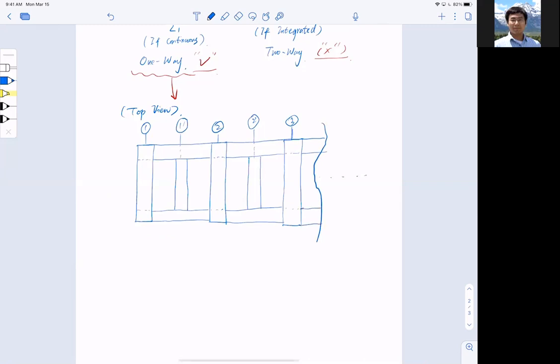Sorry, I'm trying to draw as clearly as possible. This is still an ugly drawing, but anyway. You see immediately that I have some overlapped column support underneath. I need a column underneath this transverse beam, so the shaded areas are the columns. And in the transverse direction, I call this A and I call this B. So that is the more detailed drawing for the one-way slab.